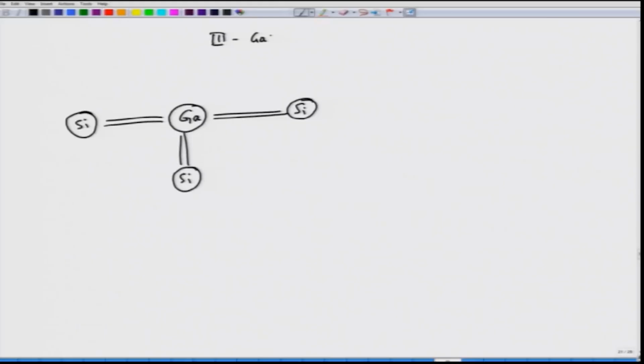It is not necessary that you actually use gallium, in fact, it is not used at all. The doping is typically by boron. So, let me go to boron, which is a group 3 element commonly used to substitute a few of those silicon atoms.